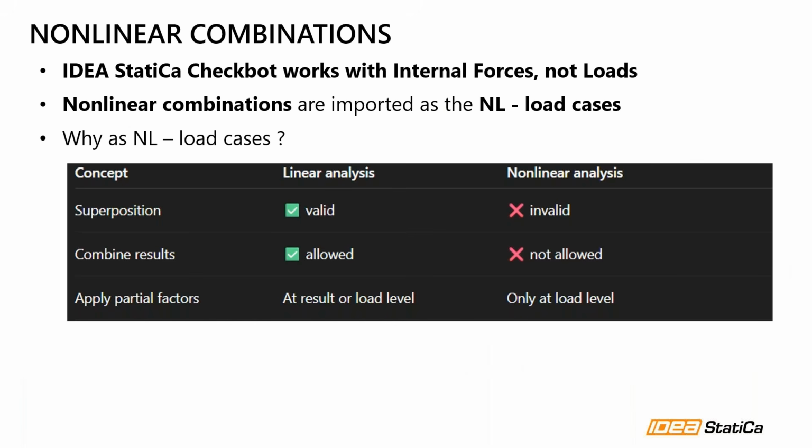So as you probably know, Checkbot works with the internal forces. We are not working with the loads. We are just taking the internal forces from the nodes and the members and going to Checkbot. So we are importing the internal forces. This is the reason why we need to upload the nonlinear combinations as nonlinear load cases, because there are some consequences if you are using linear and nonlinear simulations.